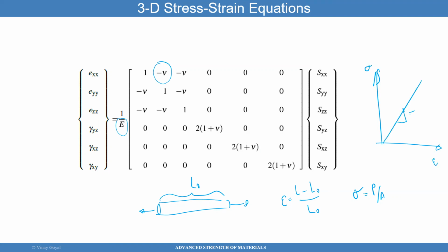And that slope is the modulus, and the Poisson ratio is easily calculable by putting a strain gauge this way. And that strain gauge is going to be the minus nu of epsilon xx, and I have this strain gauge. That gives me this number, that gives me this number, and from those 2 numbers I can calculate nu. Right? So that's how you do it in experiments, fully done, fully doable.